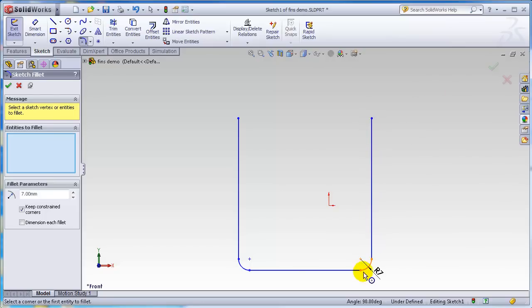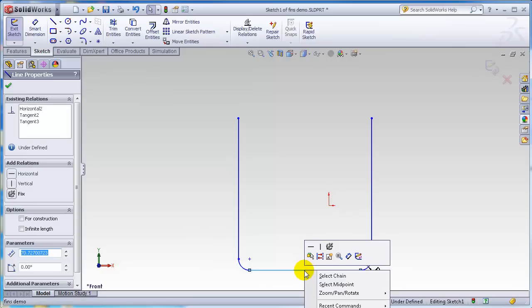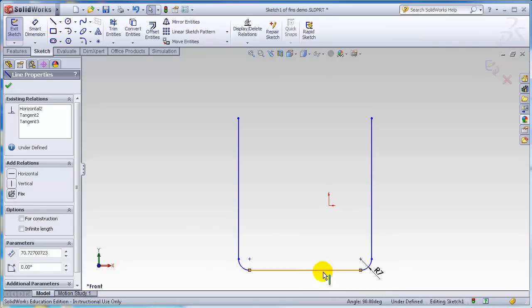Right now this geometry is just floating out here. No, I guess I will fix the one thing that will be important, because I hate to leave this geometry floating. What I would like to have happen is I'd like to have this geometry centered and symmetric about that point. And so I'm going to right click on this line, and this is something we maybe haven't shown you before, and I'm going to select the midpoint of that line.